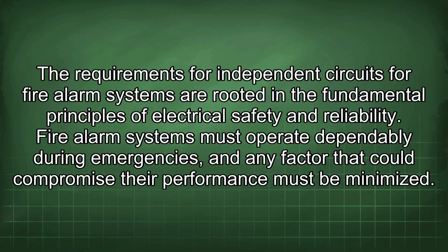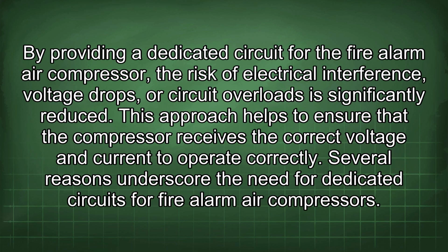The requirements for independent circuits for fire alarm systems are rooted in the fundamental principles of electrical safety and reliability. Fire alarm systems must operate dependably during emergencies, and any factor that could compromise their performance must be minimized. By providing a dedicated circuit for the fire alarm air compressor, the risk of electrical interference, voltage drops, or circuit overloads is significantly reduced. This approach helps to ensure that the compressor receives the correct voltage and current to operate correctly.